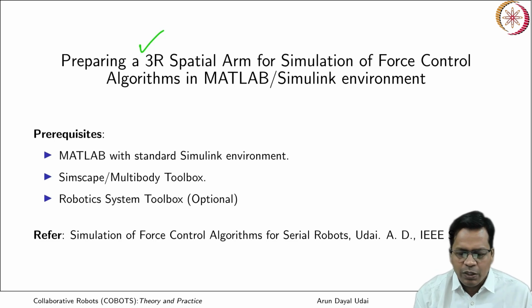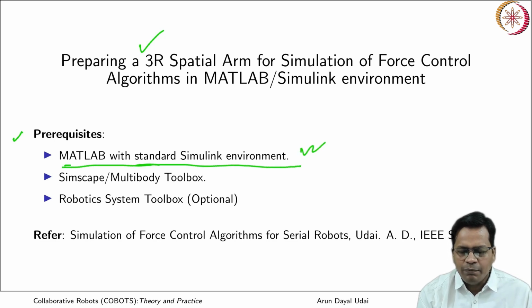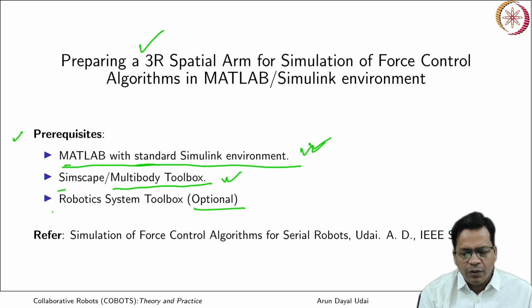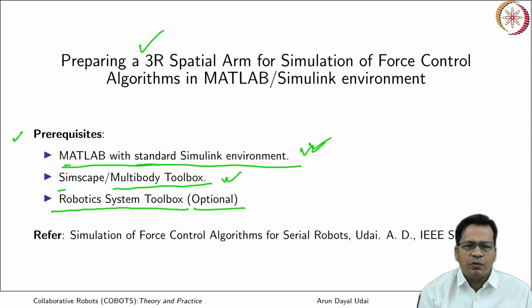To make things very simple, the prerequisites would be MATLAB with a standard Simulink environment, any version of MATLAB. I would require the Simscape Multibody toolbox to create my robot and do my closed loop operations. Additionally, and this is optional, you can have the Robotics System Toolbox, which can take care of gravity torque and calculate the robot Jacobian.